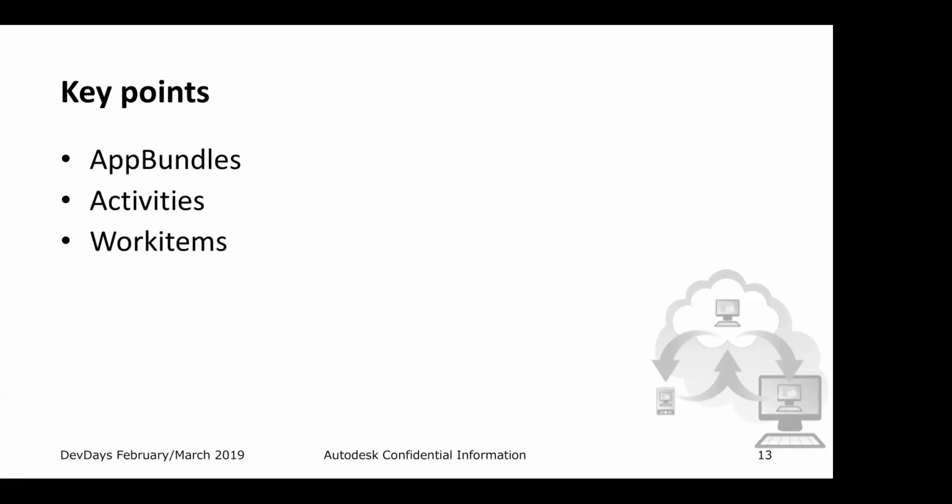Every time that you execute a work item, you can look at the status of that work item, and at the end of the work item, you can get the output. On that image that I showed before, you can see the entire output that is coming from the engine, telling it's downloading the files, it's executing your code, and you can see part of the problems, right? But the best way is to handle the errors inside your code. Remember, this is a batch operation, and you're not expecting user interaction within your bundle. So you need to handle all the possible scenarios.